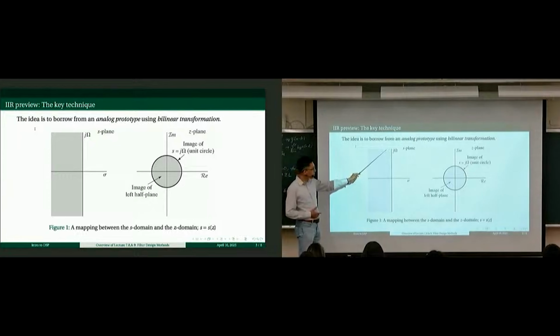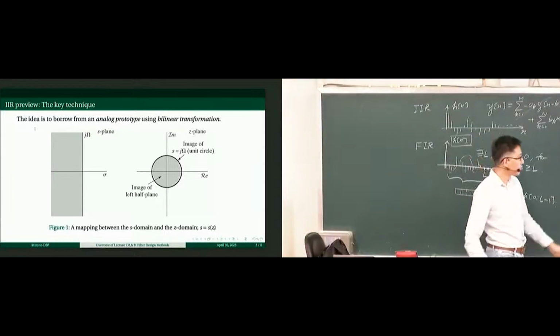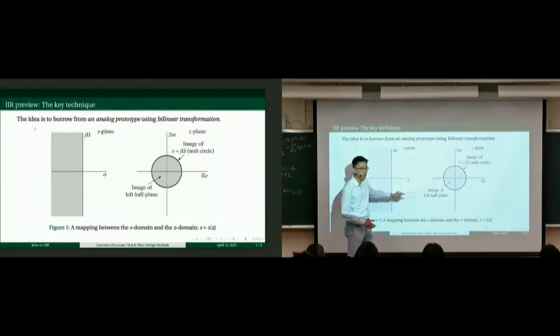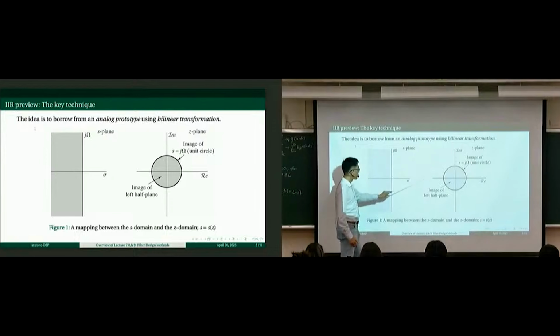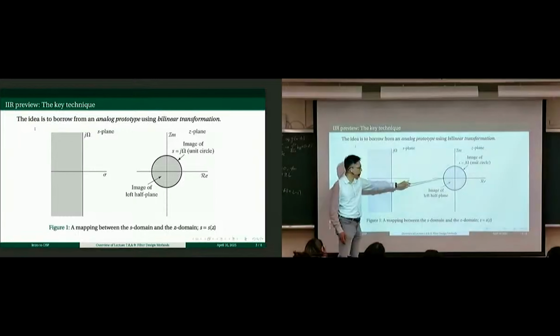Then it turns out that after the bilinear transformation, you will be going around the unit circle, starting from way at the bottom, around the unit circle in the counterclockwise direction. 反时钟的. Let me repeat that. If you go up, it's equivalent to going counterclockwise in here. With DC mapping to DC, that's DC frequency for discrete time, and infinity mapping to pi. Yeah, so there is a map to this frequency, frequency pi.